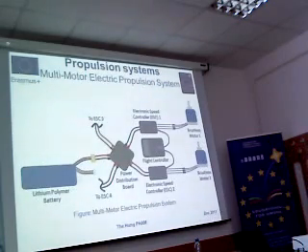And this is the full scheme of the multi-motor system. So you can see here, now we don't use the receiver, we use the flight controller. For example, the flight controller will control ESC 1 and 2, and if we connect 3 or 4, it will control all the ESCs, and each ESC will control its own motor.